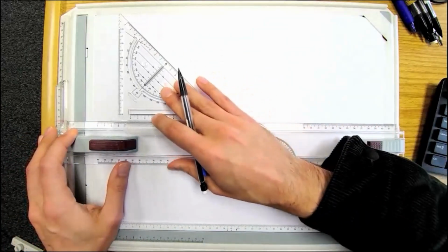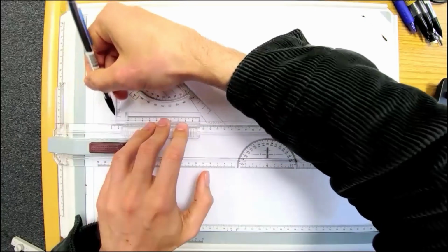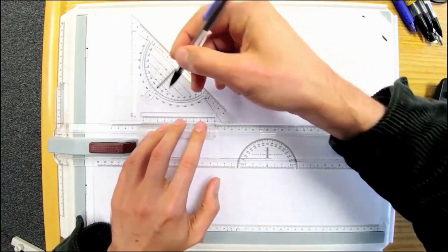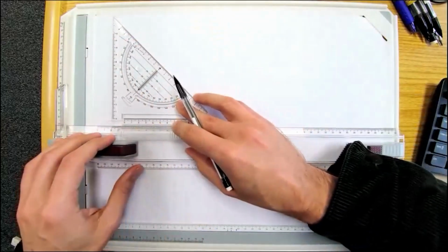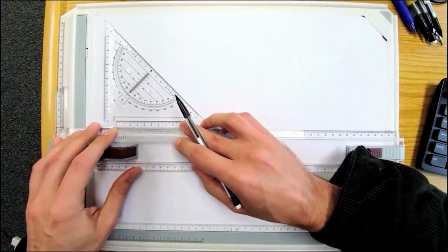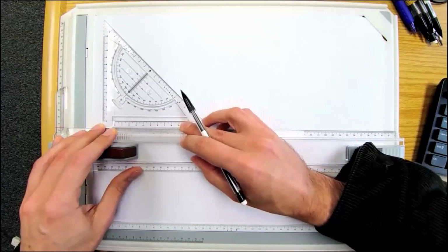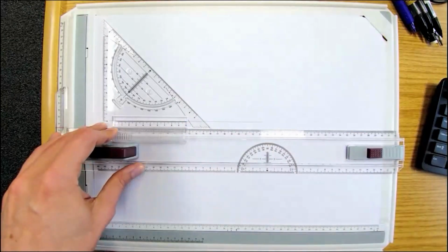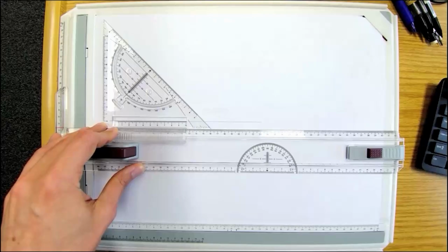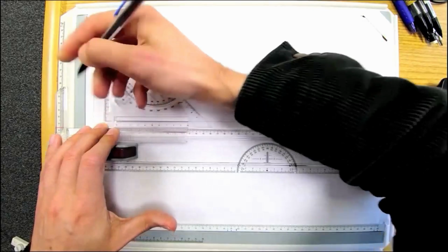So the first line we want to draw, again, I'm using construction lines first. It doesn't matter really the height of this column for now. And then I'm just going to mark here the thickness of this column, right? The thickness is, if I'm not wrong, 200, right? 200 divided by 50, that's 4 millimeters. That's our column.